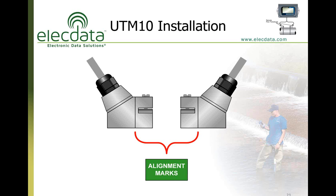The sensors have alignment marks on them. One of the things that you'll be prompted for in the setup is a recommended distance or spacing between the 2 transducers. So you can run a tape between those, and one of the first things that we recommend is that, either watching the display or the software, you have it set in signal strength mode. You can see as you're installing the transducers and as you move them around whether the signal strength is increasing or decreasing, and you can strive for the maximum signal strength.